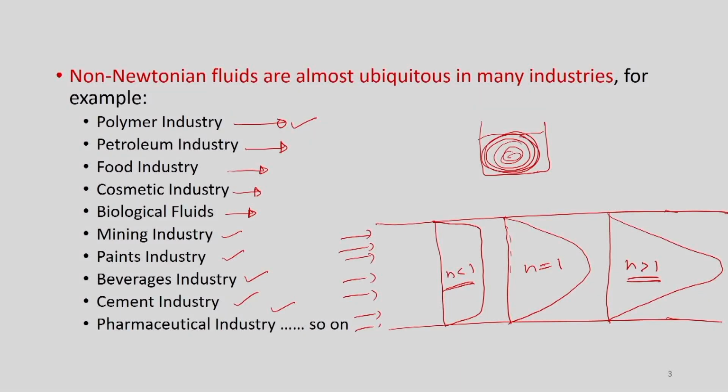So, definitely, if you start designing your process assuming the fluid is going to be a Newtonian fluid, then the friction factor in this case, as in general, is 16 by Re. But when you use this design for power law fluids, non-Newtonian shear dependent viscosity fluids, then you are not going to get the same performance as you expected for a Newtonian fluid,